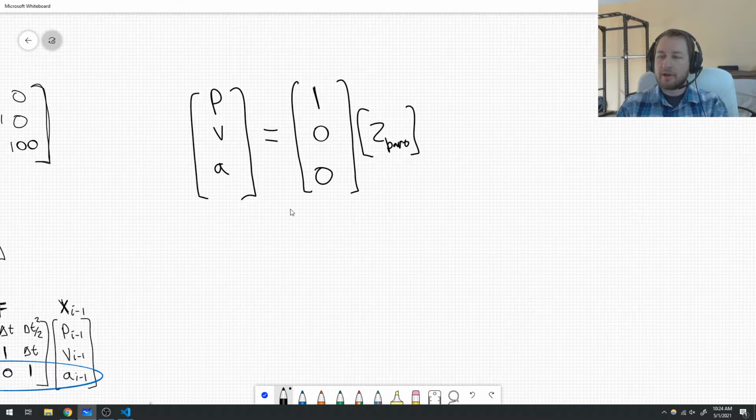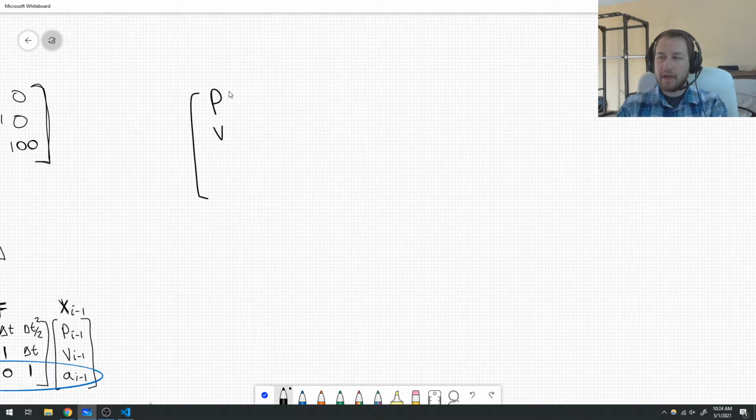With the Kalman filter, we're not actually converting the measurement into a state. For the purposes of the Kalman filter equations, we're converting the predicted state that we thought we were at into the measurement we thought we would get. So we would write this differently, more like this. We have this Z barometer, this is one number, equals our state.